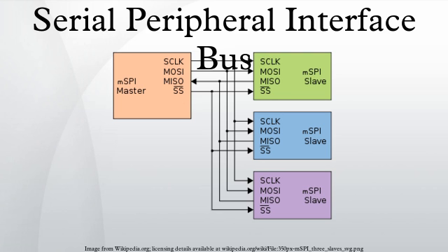The key parameters of SPI adapters are the maximum supported frequency for the serial interface, command-to-command latency and the maximum length for SPI commands. It is possible to find SPI adapters on the market today that support up to 100 MHz serial interfaces, with virtually unlimited access length.